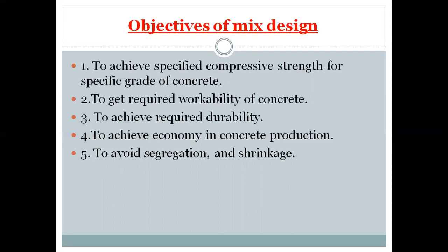Second is to get the required workability of the concrete. Depending upon the type of the work or the quantity of reinforcement provided in the members, we require concrete with low workability or high workability depending upon the site situations. To get this workability without affecting the water cement ratio, we have to design the mix of the concrete, to maintain the required workability and also to have the required strength without affecting the water cement ratio.